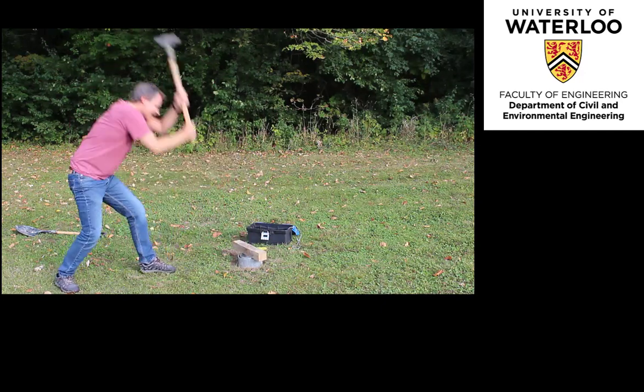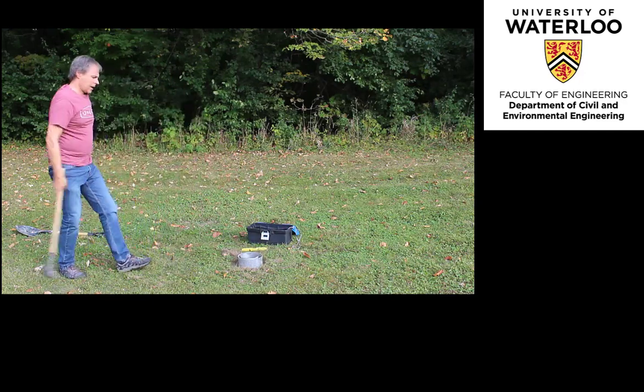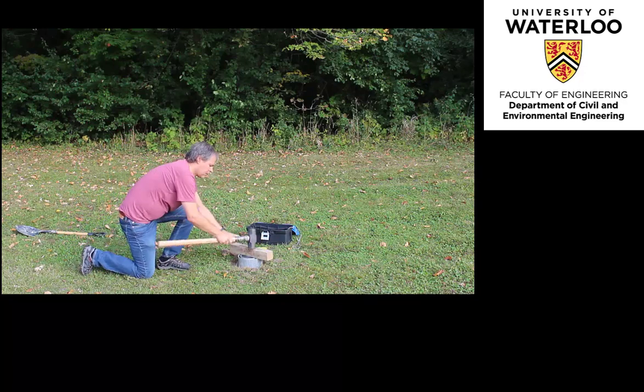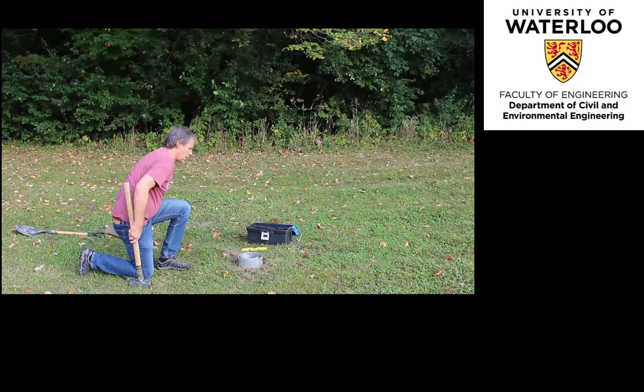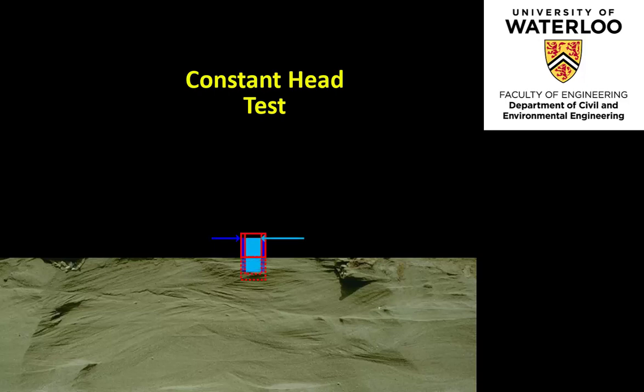The setups presented to this point have demonstrated falling head tests. However, to improve the accuracy of the test and to better control variables, a constant head test would be preferred. This can easily be achieved by controlling and quantifying the volume of water added to each cylinder area to maintain a constant height within and between the cylinders. A constant head test will be achieved by marking coincident fill lines at the same elevation datum and maintaining the given water surface throughout the experiment.